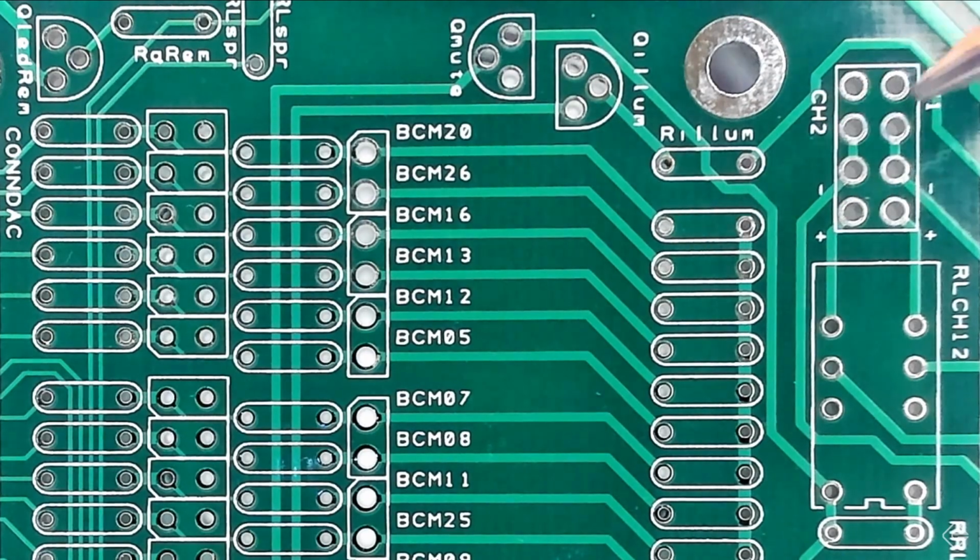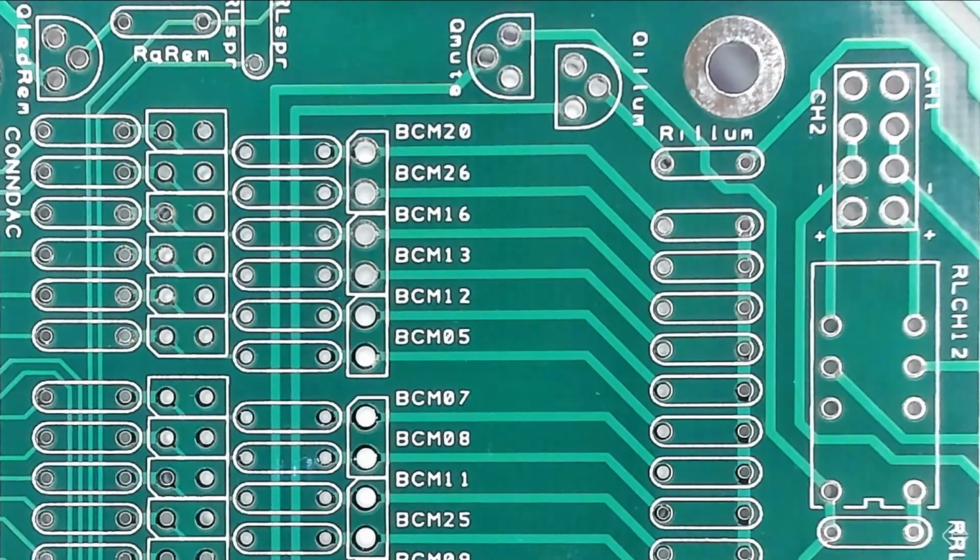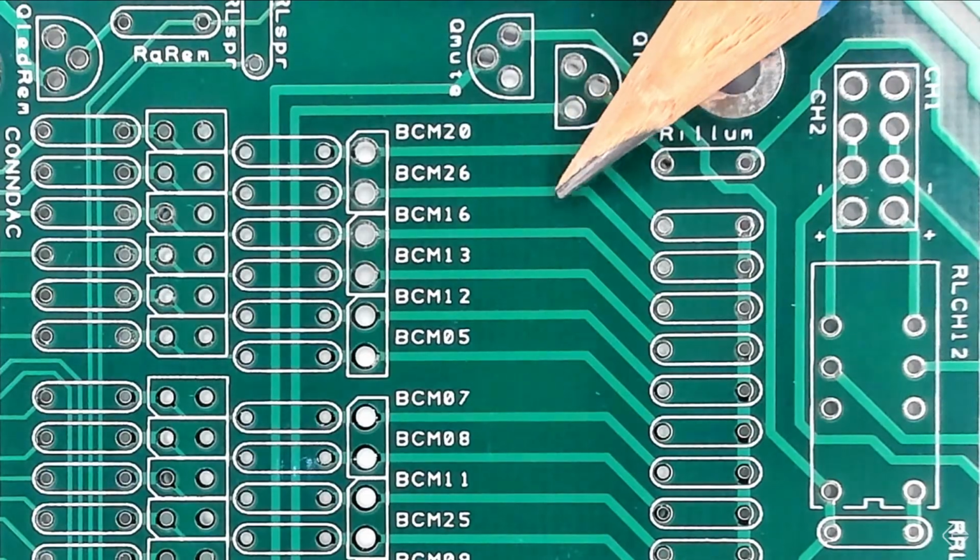So, for example, the manufacturer that I'm going to use for our circuit board says that these traces over here have a minimum thickness of 0.15 millimeters. They can't print anything smaller than that. They also say that the minimum spacing between neighboring traces has to be 0.15 millimeters. So anything closer than that, and they're not going to print. Their manufacturing capability cannot exceed that. Different manufacturers will give you different capabilities.